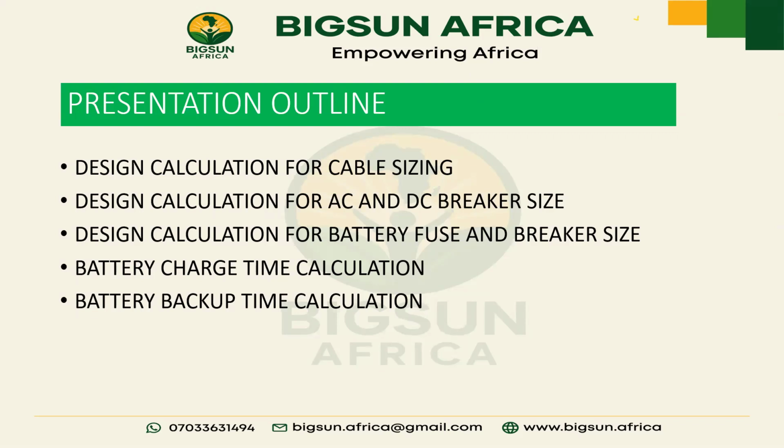Yeah, but there's a disadvantage in case there is a breakdown, maybe the thunder affected one, you'll still be using. Let's say if thunder affects your inverter, your charge controller will not do anything for you because your charge controller is a DC-DC converter. It doesn't produce AC current, but you can use it direct from the sun during the afternoon. You can't, except you have a DC bulb.